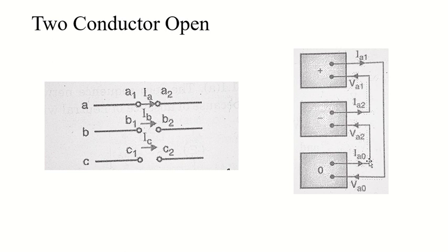So the positive, negative, zeroth sequence voltages sum will become 0 for whatever line the current is flowing through, and each sequence current will be 1/3 of Ia, because basically all three of them are in phase. Based on that equation, the diagram we will get will look something like this.